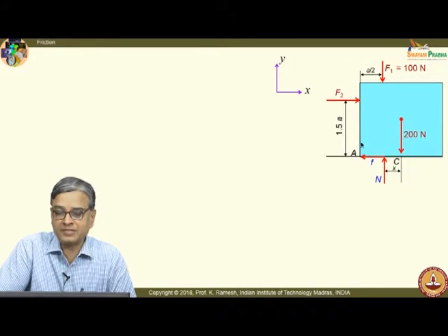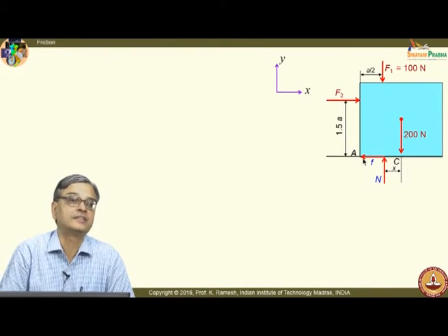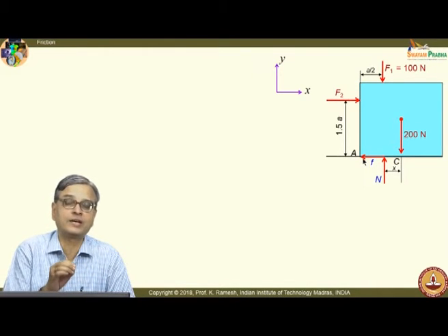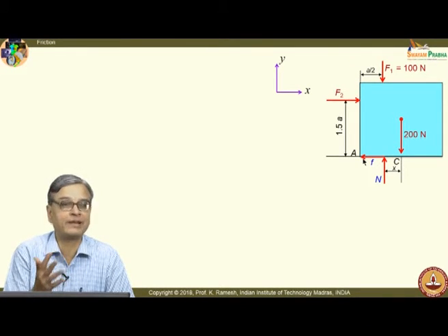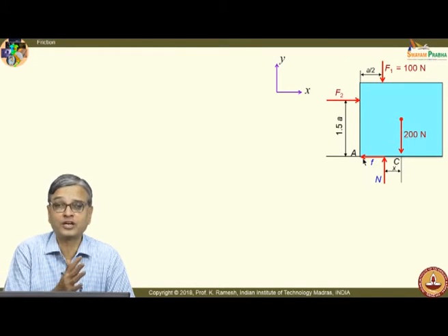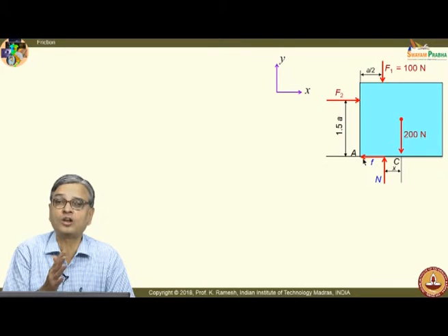And in all problems dealing with friction, if you do not write the frictional force direction correctly, you are solving altogether a different problem. So, spend a minute on observing what way the frictional forces would develop. This is very, very important. Do not rush through, because if you rush through, then you will be solving altogether a different problem.